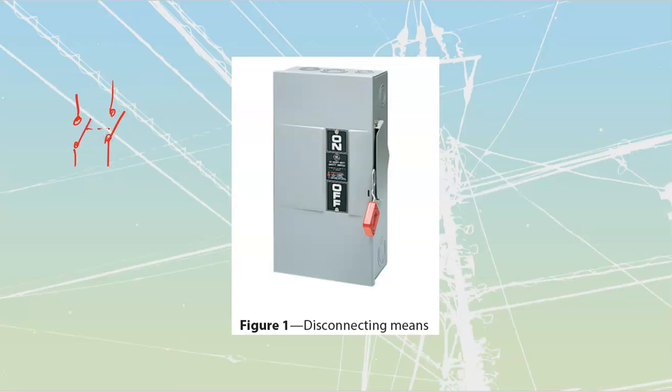This one over here would be referred to as a DP, double pole, and then ST, single throw. We throw it either into the on position or into the off position. Throw is the number of positions that it can have. This one can either be high or low, on or off. So it's a single throw. Double throw would be on, off, on, would be what we would look at. We looked at that stuff inside of our V line, though. We're not going to go back over it.